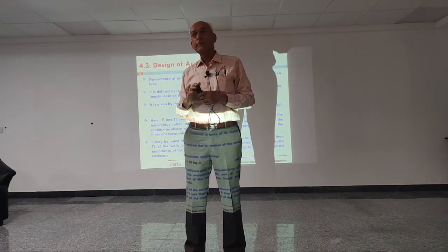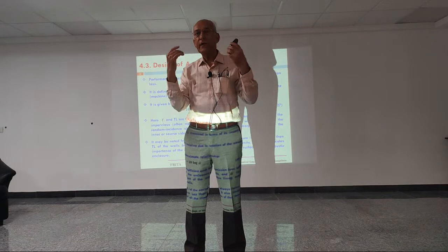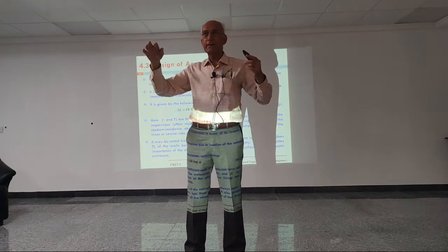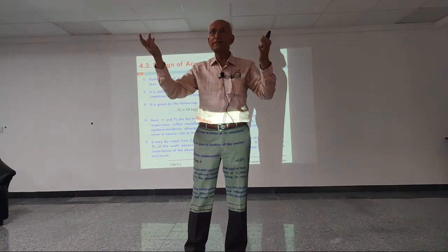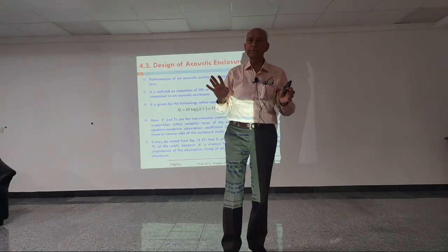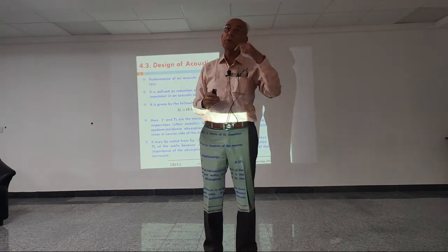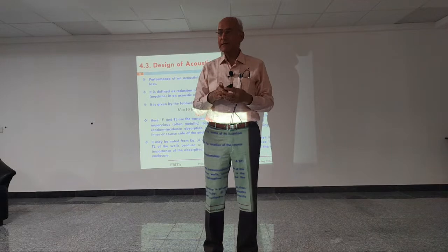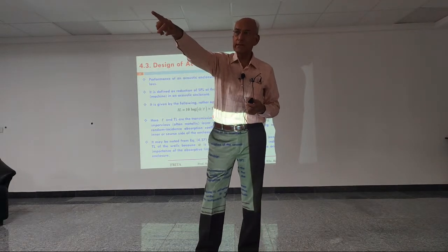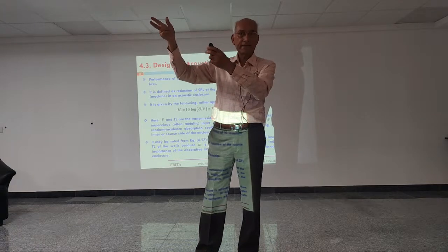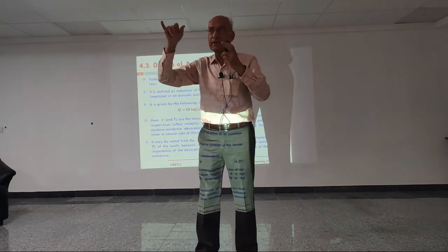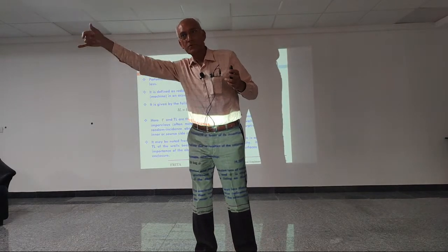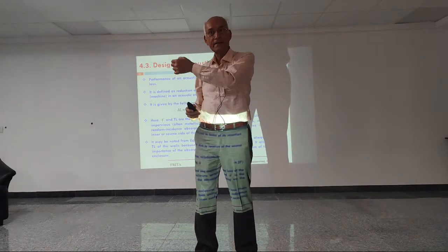And then we also compared in what kind of area that factory is going to be put up. That whole Kerala is like that, but anyway, it was almost like a forest area. So we had to apply those conditions of real quietness. Let us say I get that 100 decibel at that point, and I find that the nearest residence will be at such and such a distance. So then I find out how much this noise will be at that house. So that I came to know what kind of reductions I need.